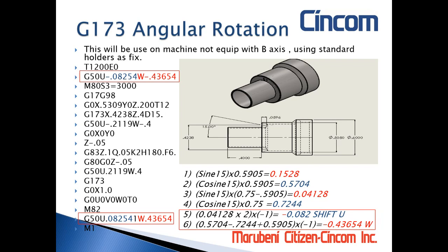That means you have to set the angle on that holder, and I will point out the right way to do that. We have scales on our machine, and I will call that up as a visual, but I encourage people to use a dial indicator. You can make what I call a dummy program, do the math, and just swipe against the holder, and you will get exactly the same angle that you need to be using.